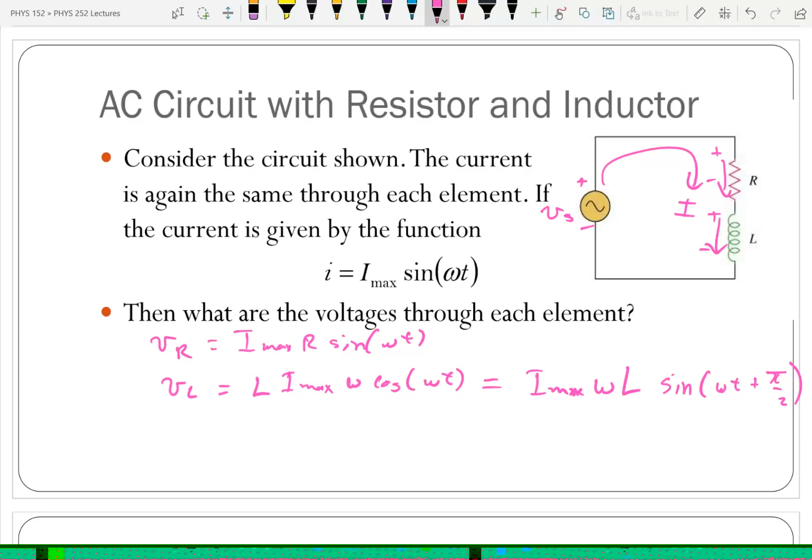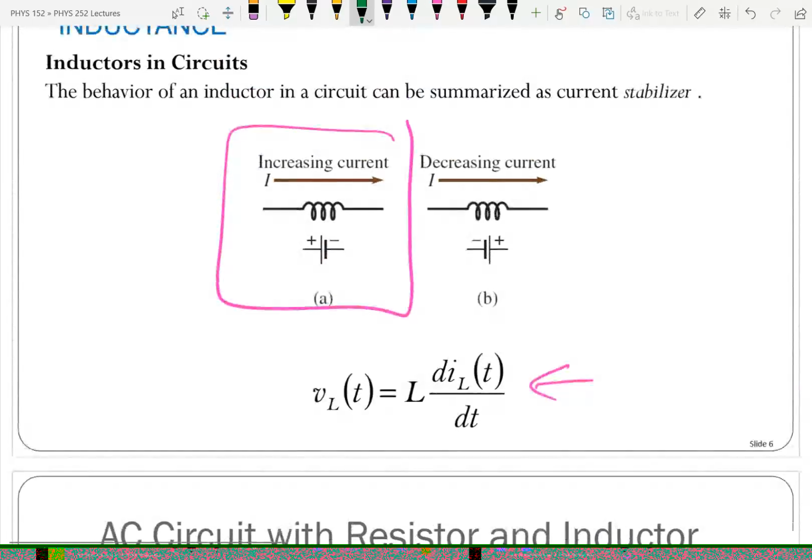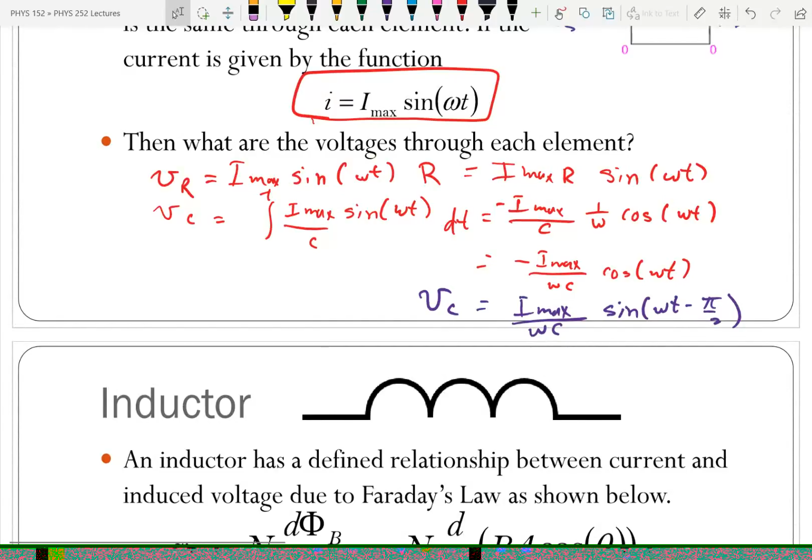Something I didn't point out last time that I need to, you can see where that naturally came in. I'm not sure what I did yesterday, but you really need calculus to actually show where the omega comes into this. And so that we call the reactance for the inductors omega L. Up here, we had X for the capacitor was 1 over omega C because the current was divided by omega C. And so the reactances are found by doing the calculus.